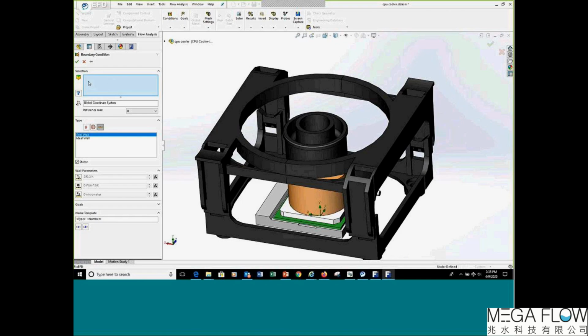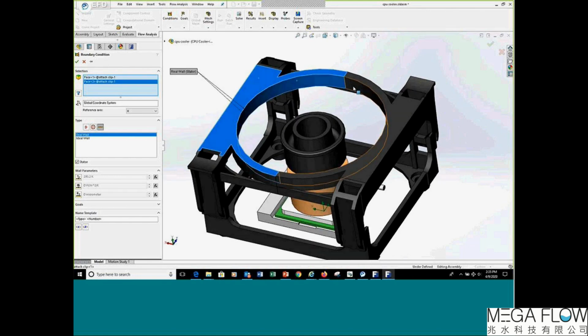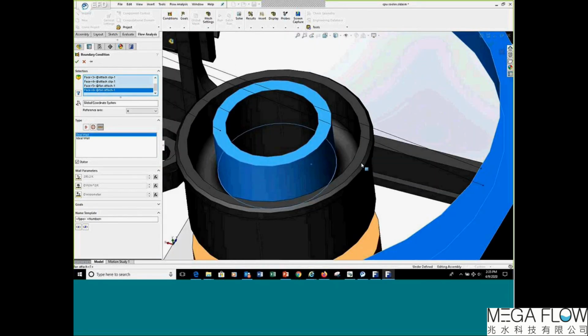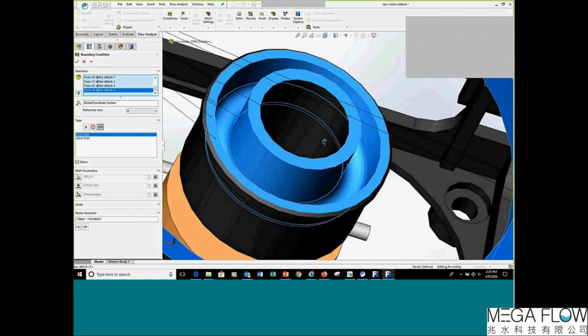And now, from my prompt box, I have to select the faces that are all part of this stationary area, where the region overlaps. Now, these surfaces are obviously larger because we know that the region really only overlaps in a circular shape here, but that's okay. The fact that the surfaces are larger doesn't really mean anything. It's redundant. We already know they're stationary. But it's important to make sure I collect all of the surfaces that really do fall within that rotating region. Okay, so there's about 10 of them here, I think. I think there's one more.